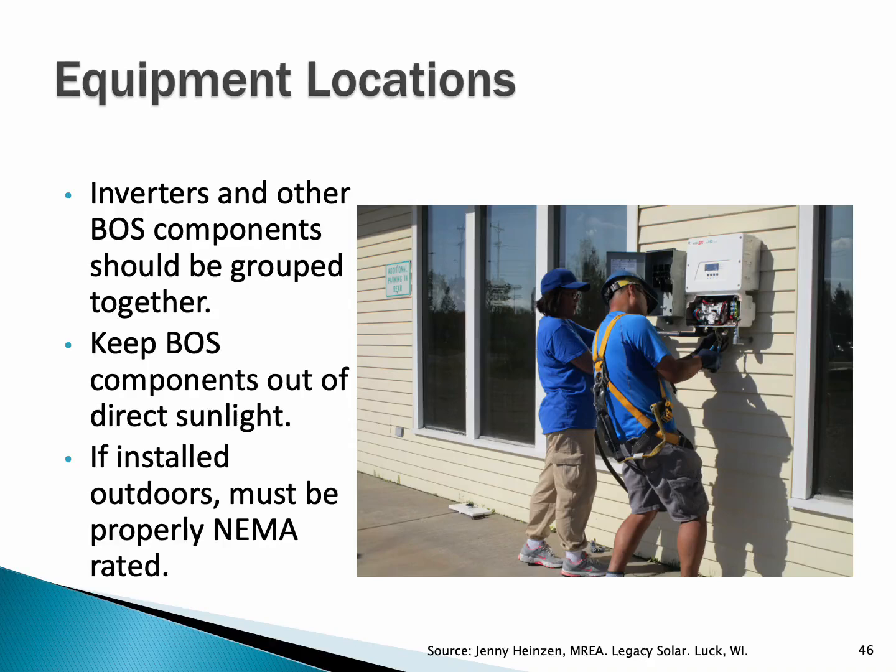Once we get those electronics over 122 degrees Fahrenheit, they start losing efficiency. So placing the balance of systems, namely the inverter, on the north side of the building keeps it cooler and more efficient.